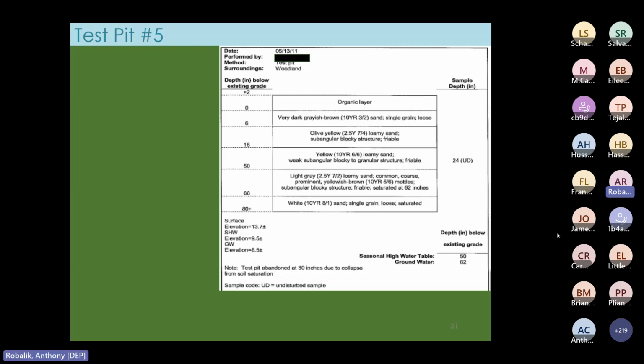So as to the question of whether or not we could accept this with only one soil profile pit in the infiltration area of the basin, in this case, since 4 others were very near the basin and the results look very similar to the profile pit that was actually taken from inside the basin, I'd say it's no problem here to just accept these even though they're not inside the basin. We have plenty of evidence here to show that the water table is low enough to have that required 2-foot separation.